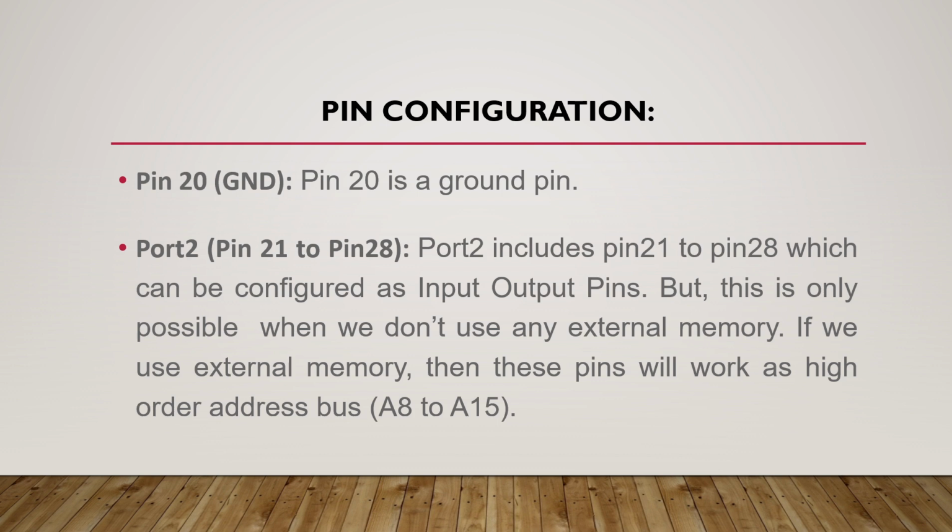This ground pin we have to connect to ground. Okay, next, port 2 pins are pins 21 to 28. This port, pins 21 to 28, can be configured as input output pins, but that is only possible when we do not use any external memory. If you use external memory, then these pins will work as the high order address bus.